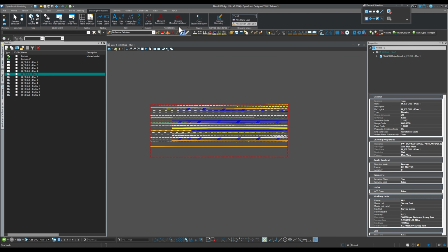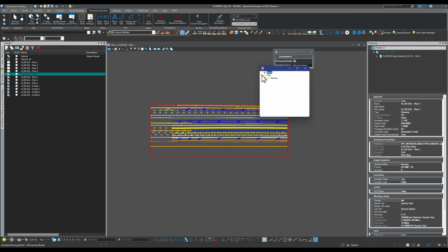Okay, now let's annotate the drawing models. In the Florida workspace, when it comes to the plans, the only annotation that they have here is the north arrow. That's all it's going to do for you. You click on it and it brings it in for you. But other workspaces have some extra annotations. Some of them are actually way fancy. They have match lines too. And FYI, per Florida as of 2026, per FDM, we do not need match lines. They are not needed anymore.